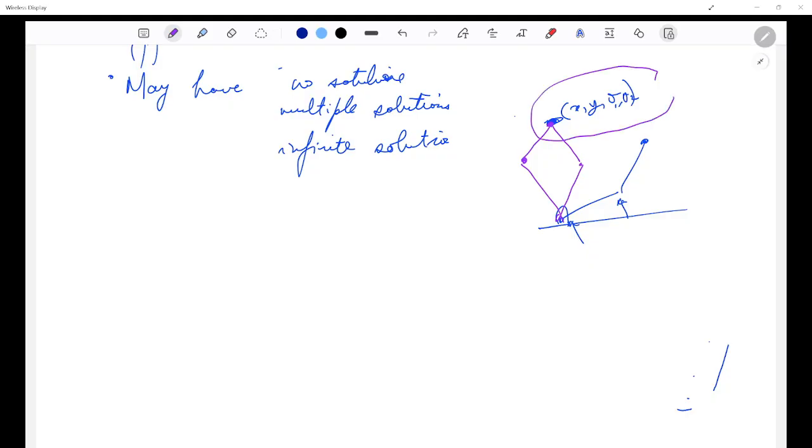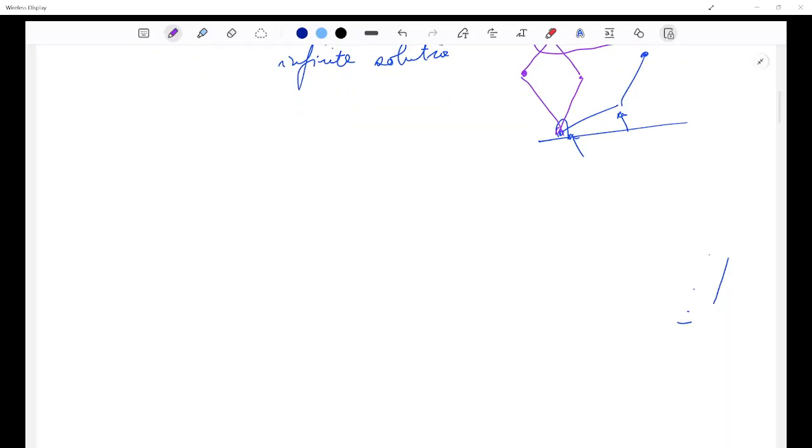if you have just these conditions defined, and then you want to find out what the joint variables are. You might not have a unique solution; you have two solutions in this case, but think of it as a planar robot and you're able to understand this easily. But if it happens in space and if it is a combination of many links, we don't know how many solutions are possible. It can be many ways in which the same thing can be achieved. So doing inverse kinematics is a bit difficult. Sometimes we also need to solve an optimization problem.